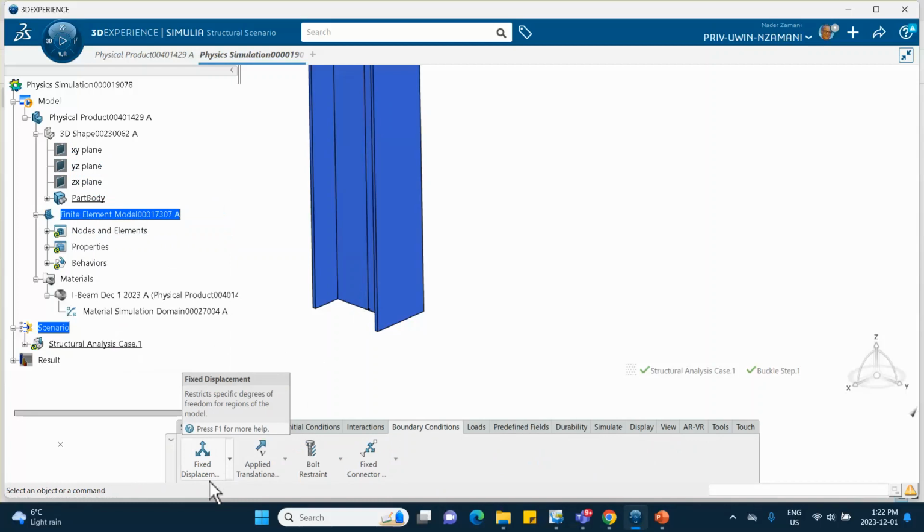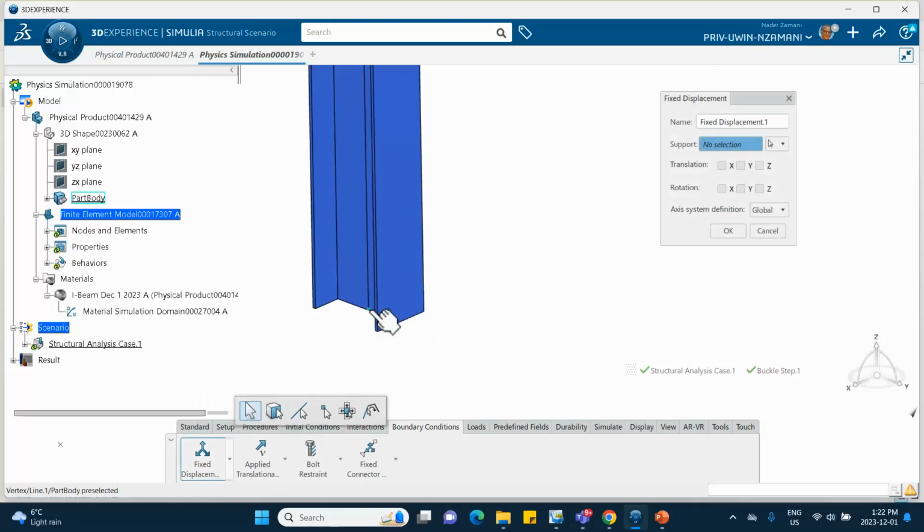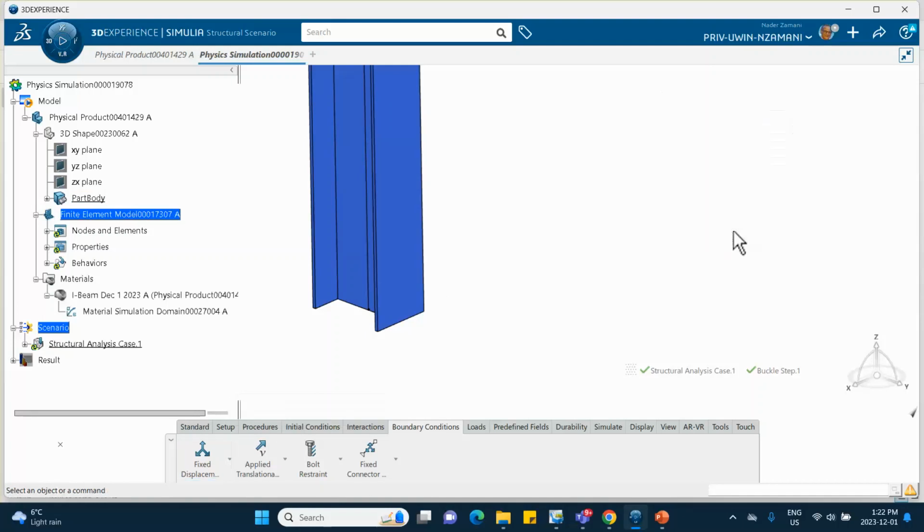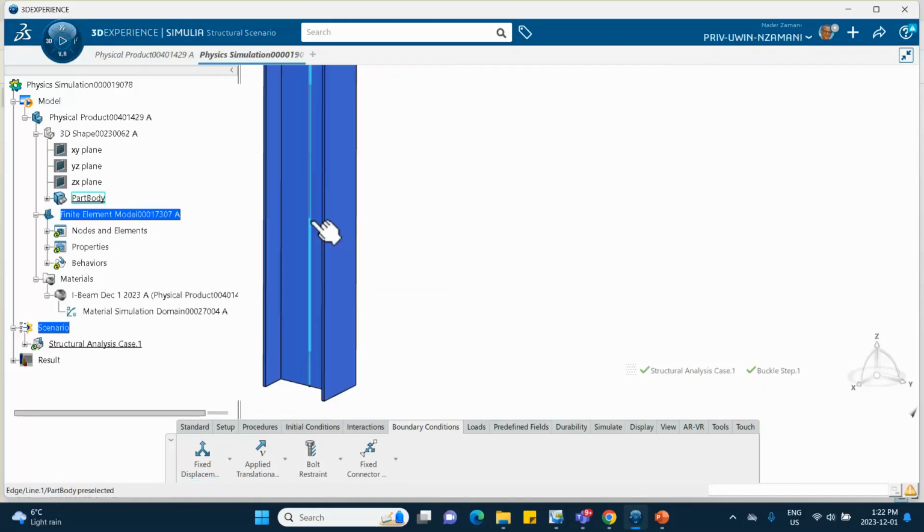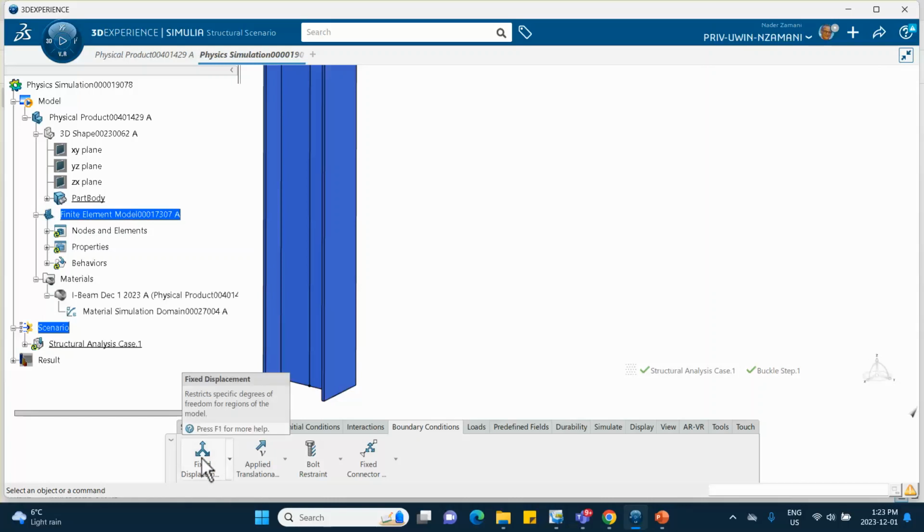fixed displacement. The bottom is clamped. All 6 degrees of freedom, 3 translations, 3 rotations are 0. Or I could have used clamp. That's fine. Now, I want this beam to move in the direction X, I wanted to say in the YZ plane. Okay, that being the case, remember, I do not have a two-dimensional element. What I have is B31, and I want to make modifications so that it essentially becomes B21. So what do I do? I go to, again, fixed displacement.